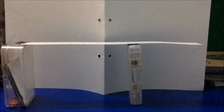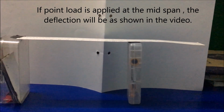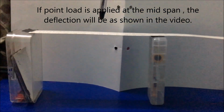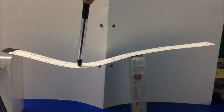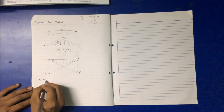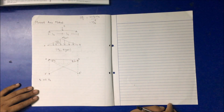As I have said, to illustrate, the very first condition is that the point load is acting at the mid span of the simply supported beam. If we see the deflected shape here, it is maximum at the point load application, and the slope at points A and B is what we have to find.